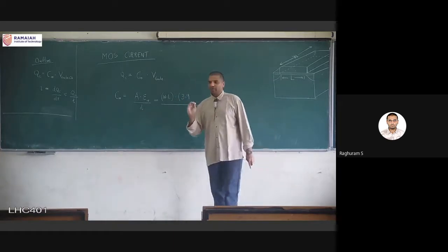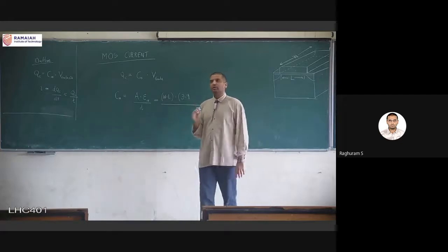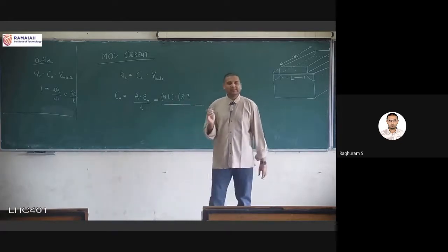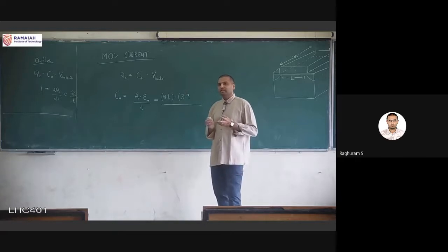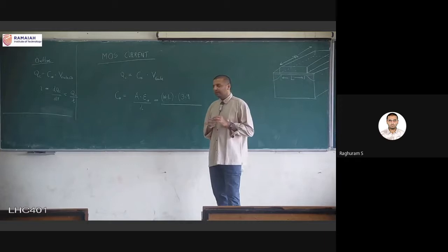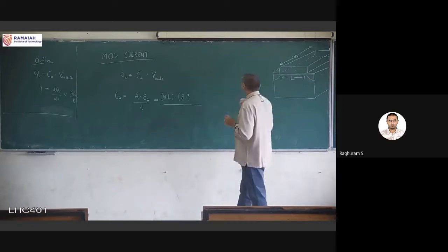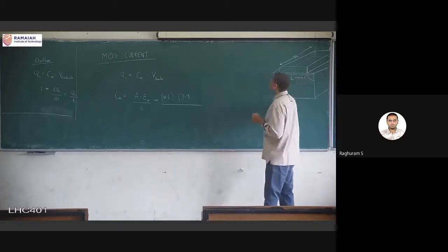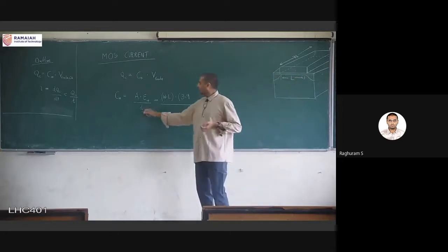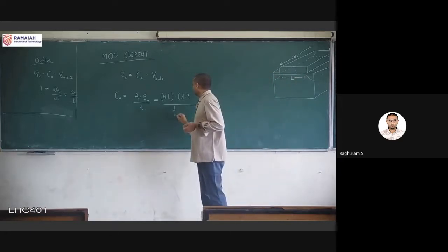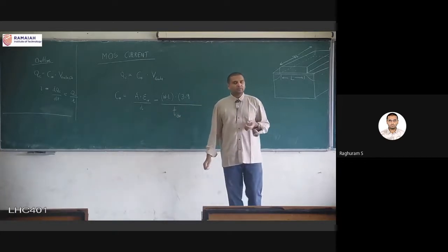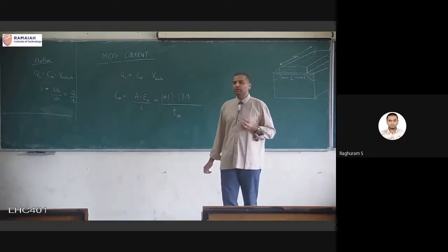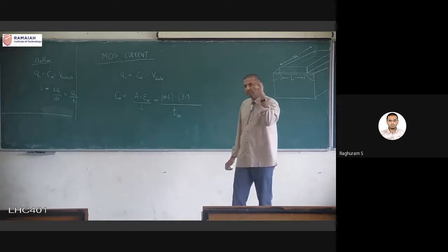Now we have also come to some more modern materials like hafnium dioxide, where the relative permittivity is higher, about 23 or 24. The reason is this oxide, this D, which is the oxide thickness. Because the permittivity was low, the oxide thickness became very, very small.